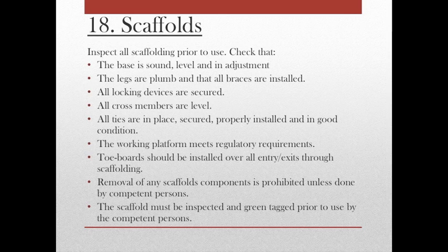All locking devices are secured. All cross members are leveled. All ties are in place, secured, properly installed, and in good condition. The working platform meets regulatory requirements. Toe boards shall be installed over all entry and exits through scaffolding. Removal of any scaffold components is prohibited unless done by competent persons. The scaffold must be inspected and green tagged prior to use by the competent persons.